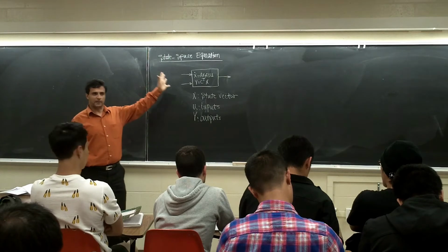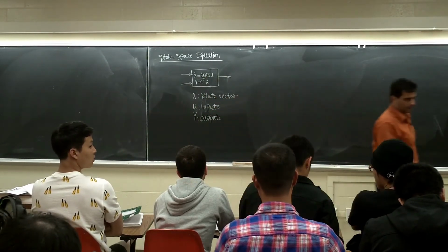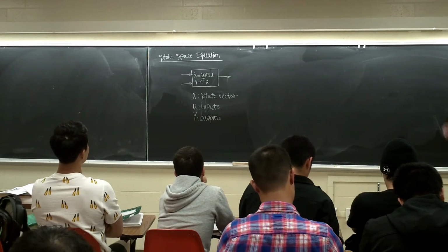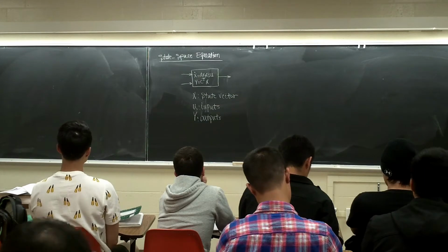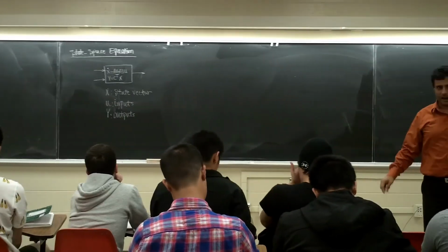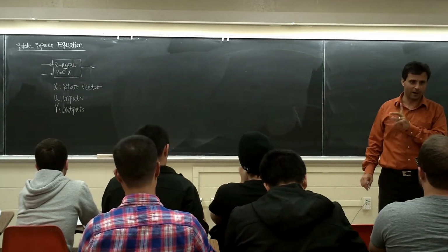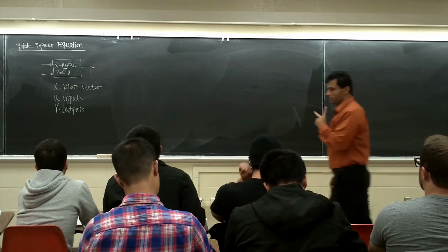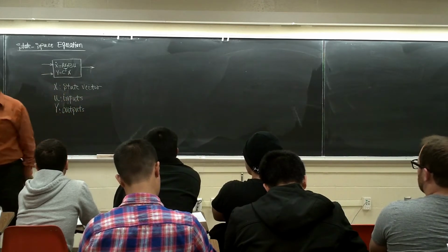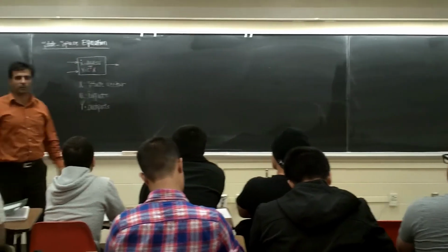For example, in the system we had, if you look at what we did here, the inputs were the VDC, how much VDC we have, and the grid voltage. Let's say we have a battery and grid voltage, right? The state variables are Id and Iq. If I know Id and Iq in that system, I can calculate anything I want, with those transformations I have, whatever I need.